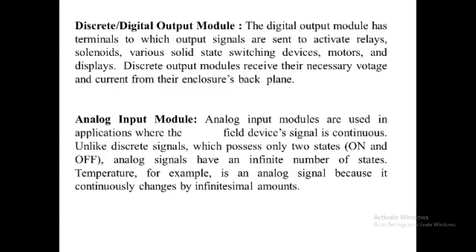And the output interface can be thought of as a single switch through which the power can be provided to control output devices. During normal operation, the processor sends an output status, according to the logic program, to the module logic circuit.